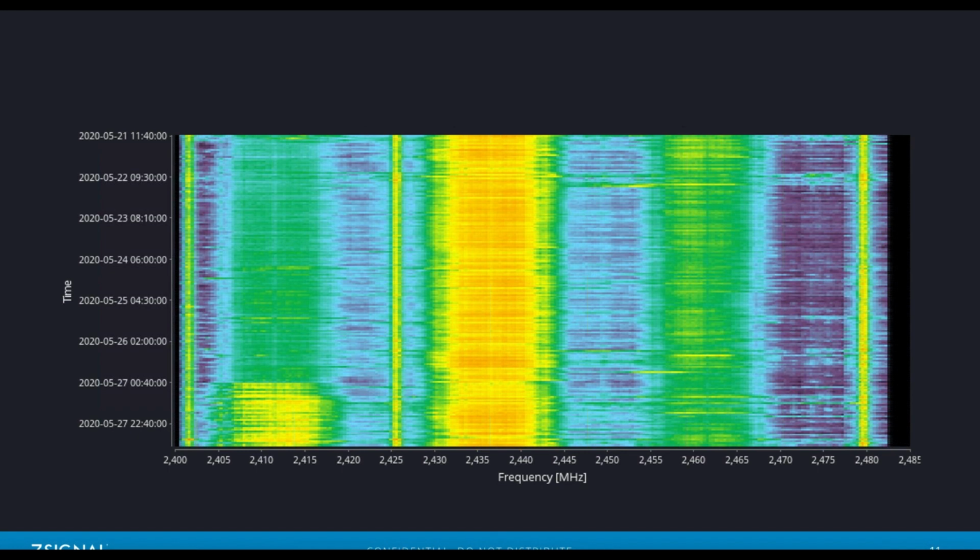That's exactly right. So when we're using 802.11b, we're using BPSK modulation, which actually has a different spectral mask. It looks a little bit different and actually spreads out to 22 megahertz, where OFDM uses 20, but it's kind of a gradual slope.